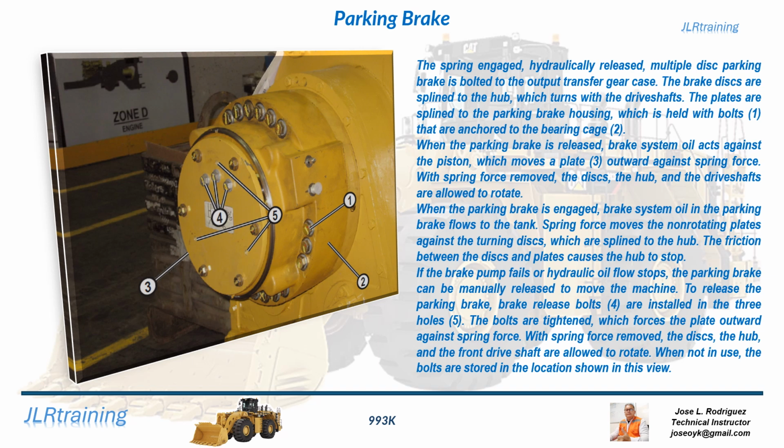When the parking brake is engaged, brake system oil in the parking brake flows to the tank. Spring force moves the non-rotating plates against the turning discs, which are splined to the hub. The friction between the discs and plates causes the hub to stop.